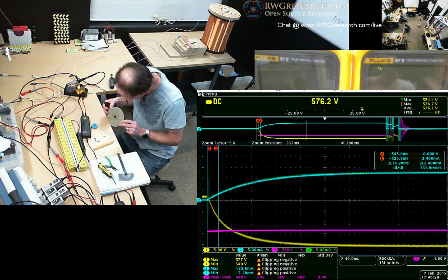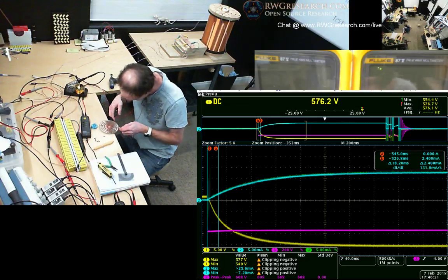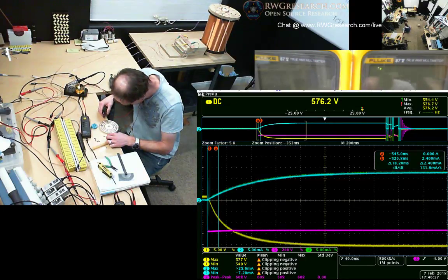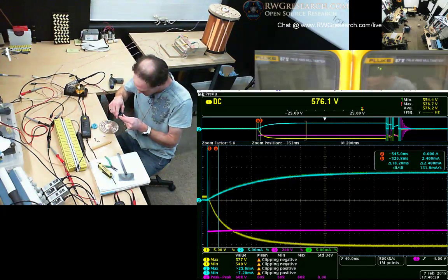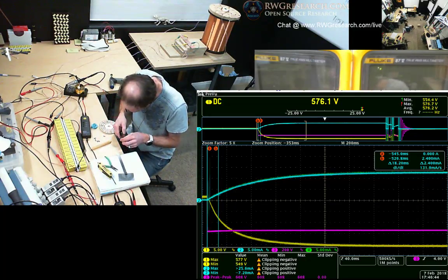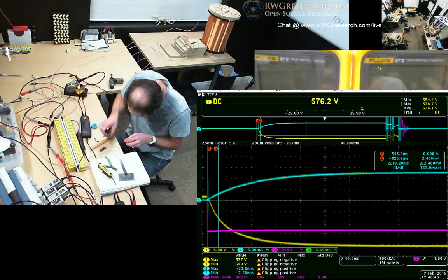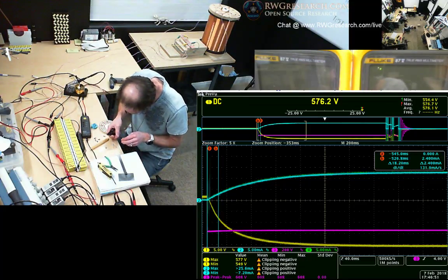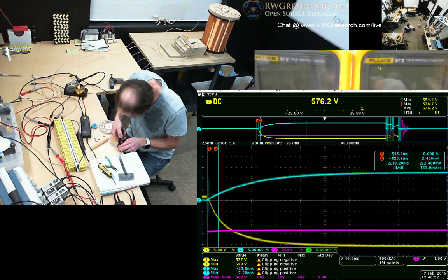What was I doing? The inside, right? The inside. That one. So I'm going to solder. This is going to be tricky. Just use a tiny little piece of wire wrap wire. I've got some silver coated copper. It's like 30 gauge, so I'm using it.